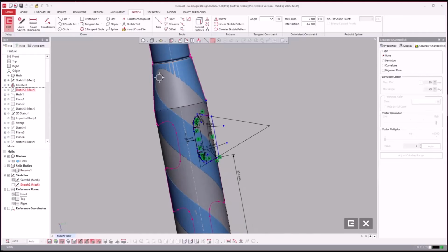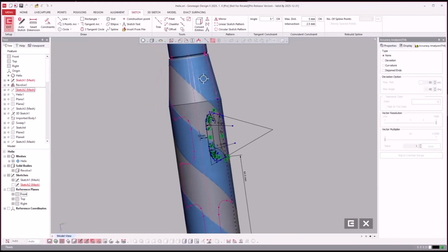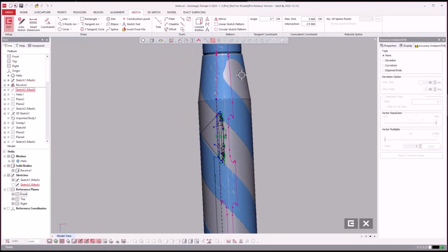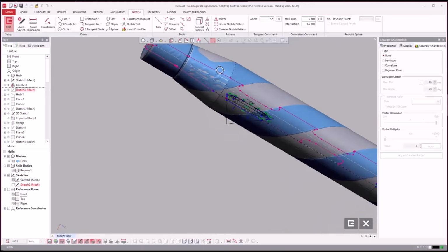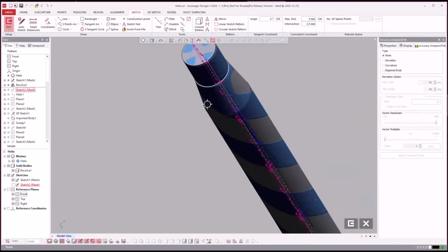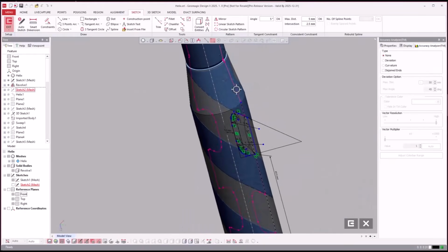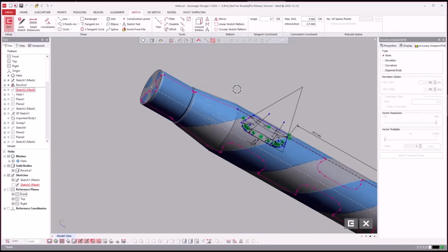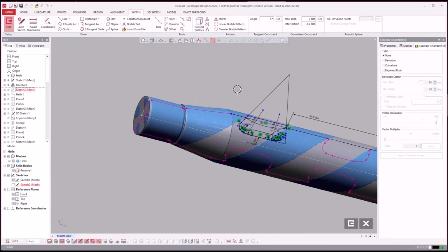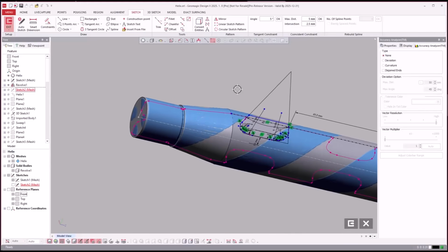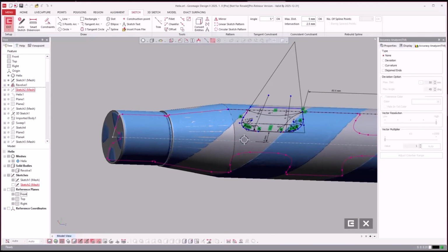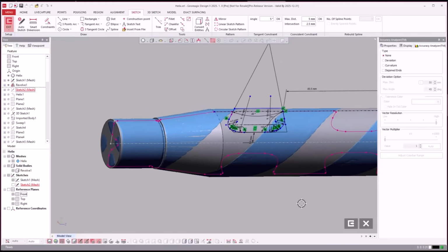So you see here, because we haven't modeled yet, there is a cavity that needs to be cut here. And if I rotate it around, there's also a cavity over here. So if I roll around, it has two starts. Not every single Helix has two starts. Like a threaded bolt, for the majority of them, only have one start, right? So it's one cut that I'm going to spiral around the outside, and that thread will thread into a threaded hole, right? It doesn't have to only have one start.